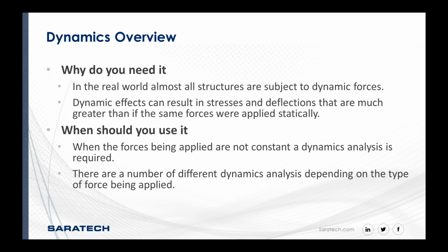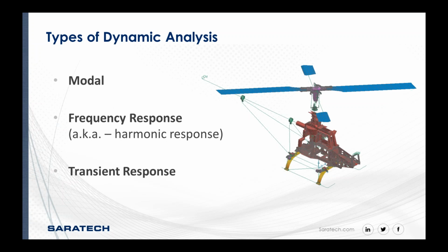So when our forces applied are not constant, a dynamic analysis is required, and this can be in the time and or the frequency domain. Here are our basic types of dynamic analysis. We have modal analysis, we have frequency response, and we have transient response. These are the ones that we're going to discuss today.